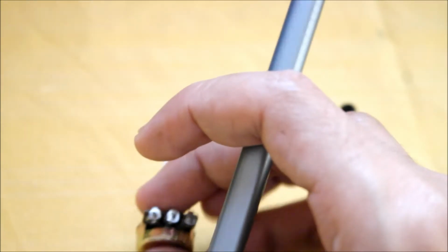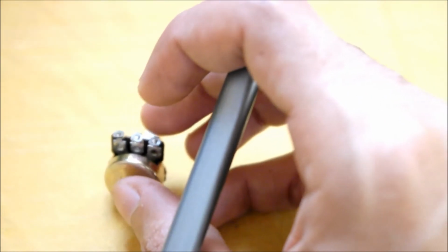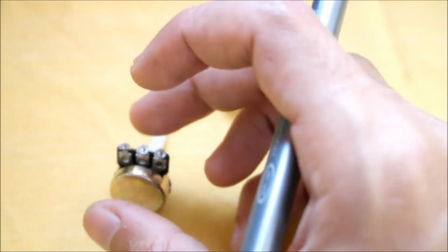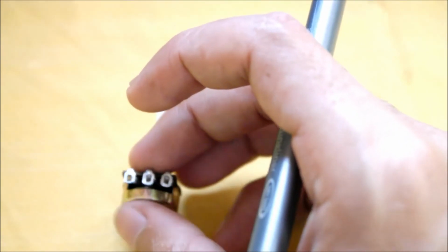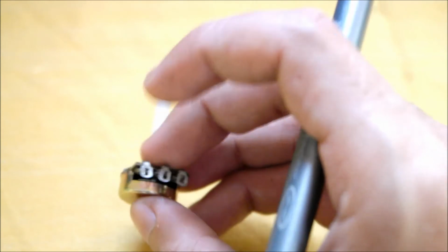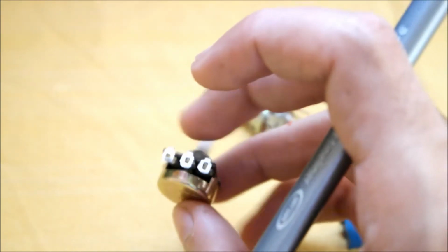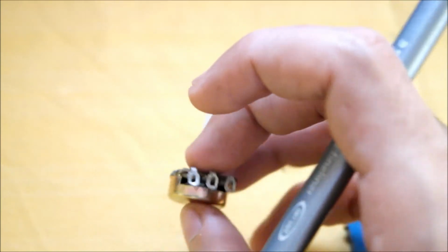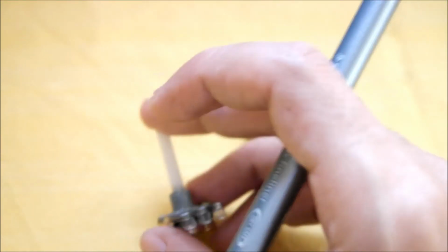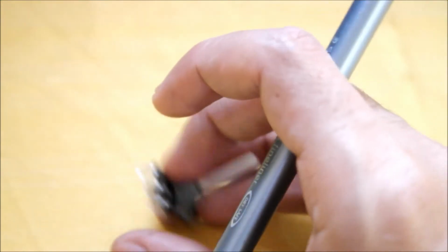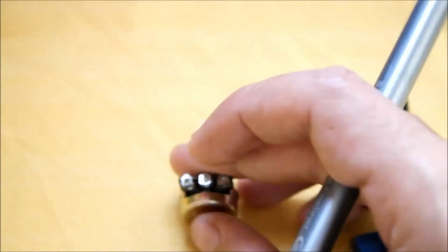So put one of your probes here and another probe here, and try to read the resistance by changing the dial within the expected range, and this will give you the maximum value of the resistance a potentiometer can offer. That's how to check the maximum value of a potentiometer, and that's how potentiometers are actually named or asked for from shopkeepers. Say, give me a 100K pot, give me a 10K pot, something like that.